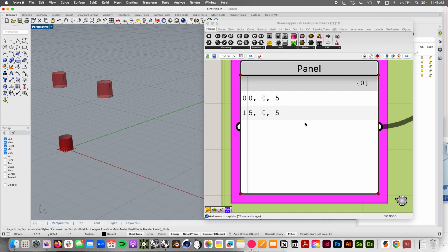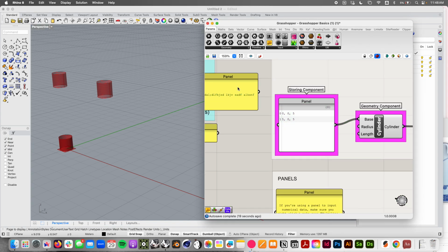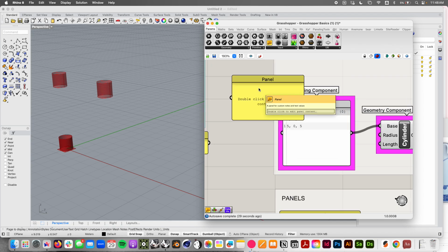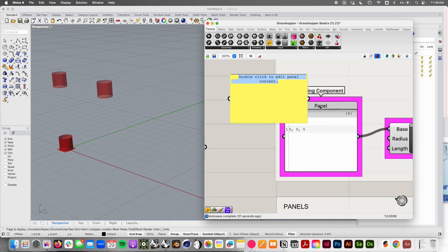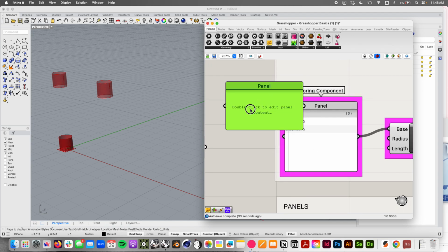If you're ever grabbing a new panel, so let's say I've got a new panel that I've grabbed from params up at the top. So params, input, little sticky note icon. And maybe I want to copy that input here. So we'll have one that's at 0, 0, 0. And then I'll have another that's at 0, 0, 10.